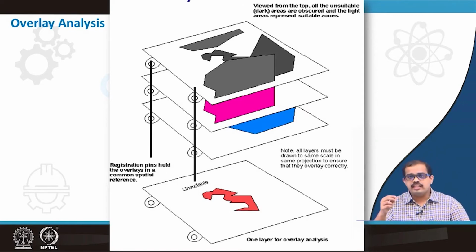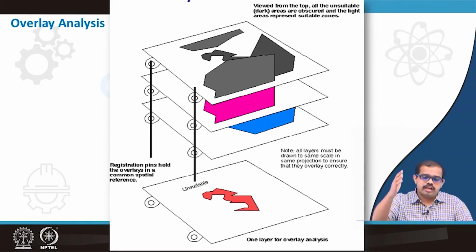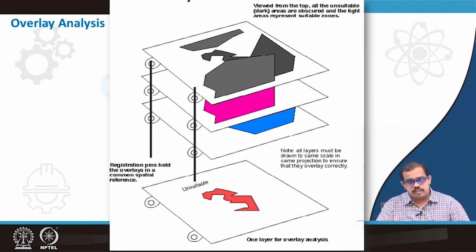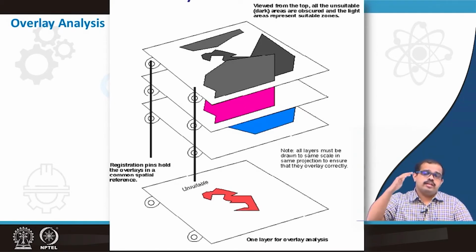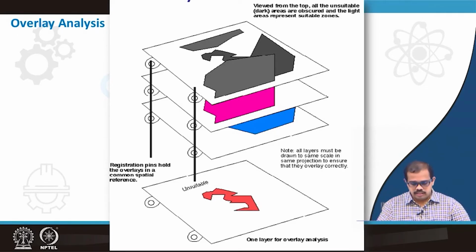So, that is one example that I have just mentioned. You can have any number of layers, any number of quantities, but these layers have to be utilized in analysis. For example, if you are using an economic layer in your urban floods, that gives you a different angle of analysis, but it may be useful for certain sections of people who are looking at your model. It may not be useful for many sections of people who are looking at your model. So, the amount of data that is necessary, the same data you will use for different kinds of analysis. That is why overlay analysis is extremely useful in GIS.